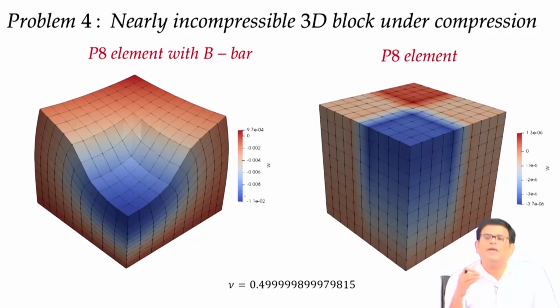So that is an advanced topic. Another one is the Hu-Washizu variational principle, which is a three-field principle involving, for instance, displacement, stress and strain, or displacement, volumetric strain and stress. The main issue is that in displacement formulation, stress is a derived quantity from the displacement.